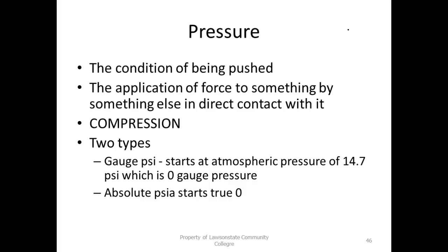If you wanted to find your true pressure, which they call absolute pressure, you would add 14.7. So if you had an absolute pressure gauge, while it's sitting there, nothing's happened, it would show 14.7 psi. Gauges show 0. Sometimes it's very important, but to us it's not, because there's so little difference that most of your gauges just use regular gauge pressure.